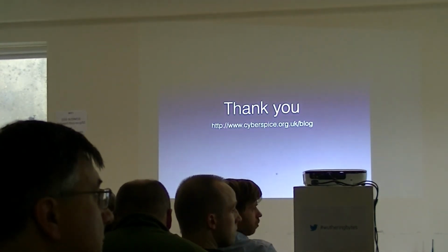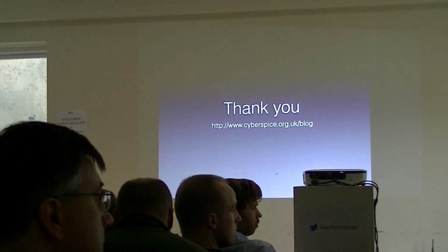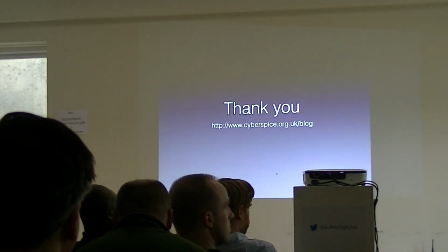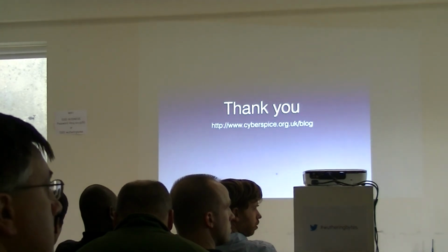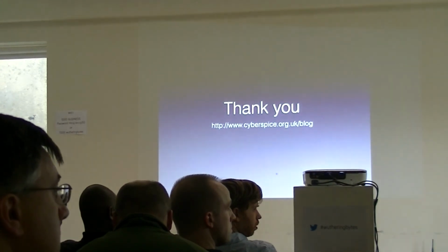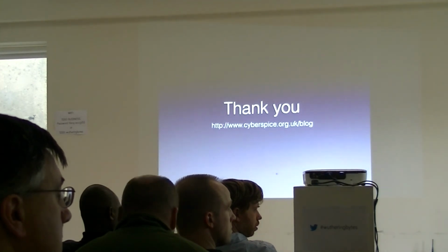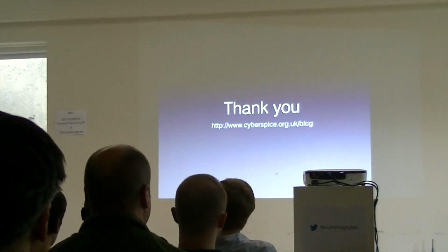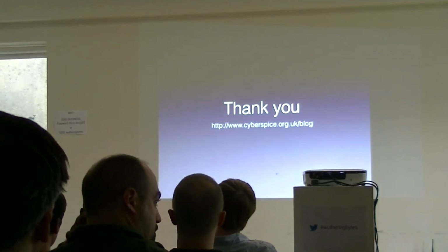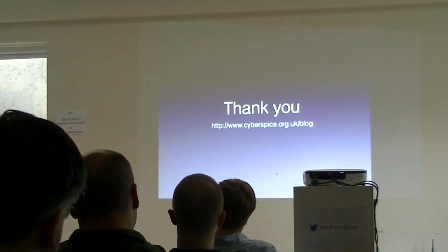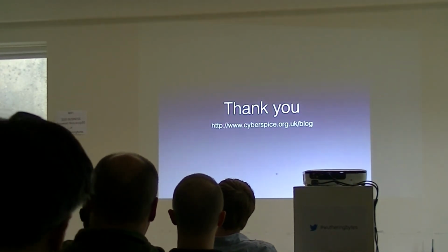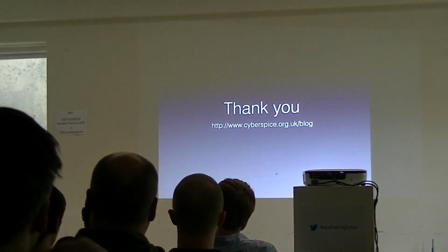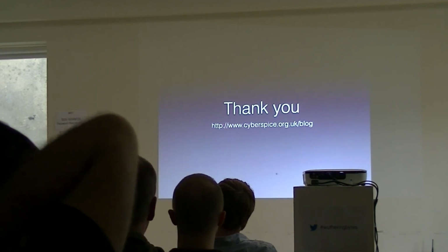I was just going to ask about the port expander, because you talked about using Linux to talk to the GPIO pins, and then you said, oh, well, it's safer if you use this port expander that uses I2C. But I would think you can't just talk to that directly through the GPIO in Linux anymore. No, you can't. You have to do a little bit more software. But as I said, if you're using Python, say, there are easy to use Python extensions out there.